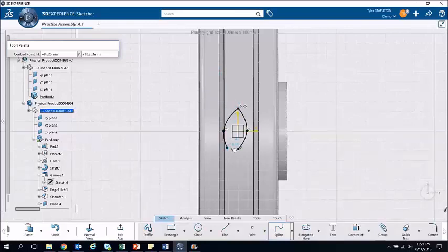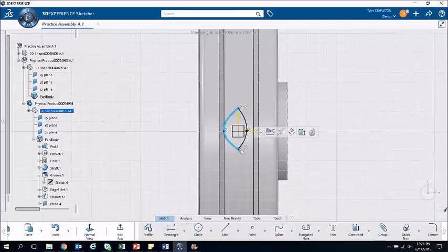I'm going to do the same thing over here, and I'm going to make sure my final point lines up as well. This is important because it's very common to create the final point to some profile that's just slightly offset from the end point on this curve. And if that happens, you're not going to be able to create any sort of solid feature out of it. So make sure that little icon shows up, showing that they're going to be coincident. I'm going to hit escape again.